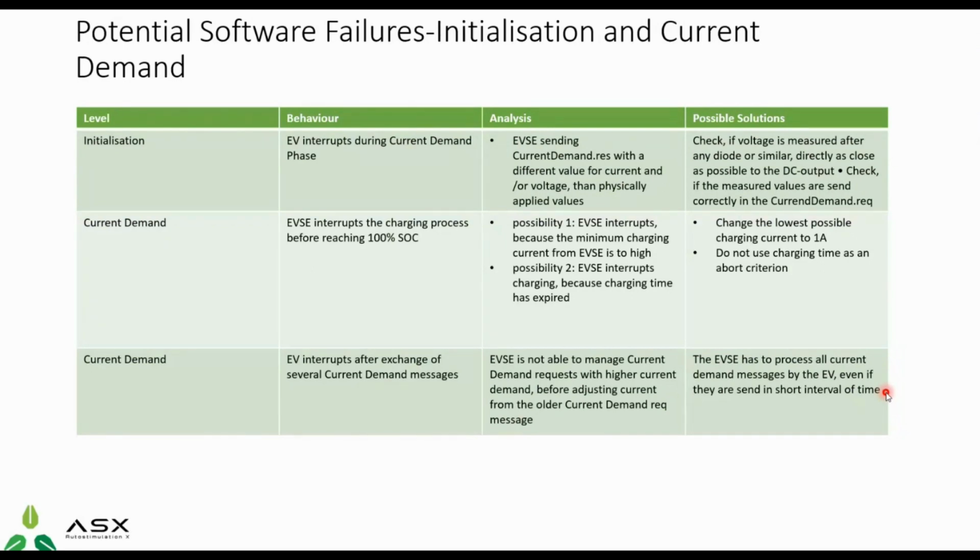Also, the EVSE interrupts charging because the charging time has expired. So the timeouts are also very important here. It is given by the ISO 15118 or DIN standard that you should have this timeout limit, and according to that standard only, the charger or the EV side infrastructure will be made. So that's why we have categorized these timeout limits also for this current demand.